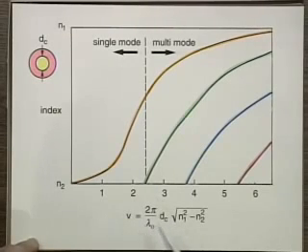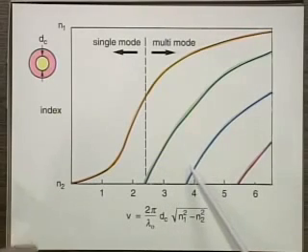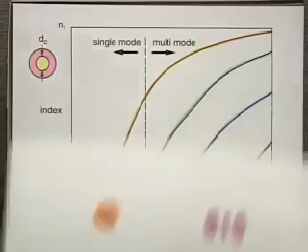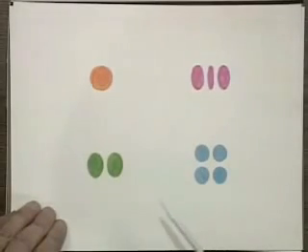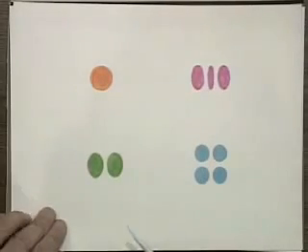In our case, we did it by choosing a fiber that has a bigger core diameter. But we could have also done it by changing the wavelength. If you just shorten the wavelength, go more into the blue side of the spectrum, then you start to see transverse modes like I showed you before. Okay, and I think now we're ready to have fun with a multimode fiber.